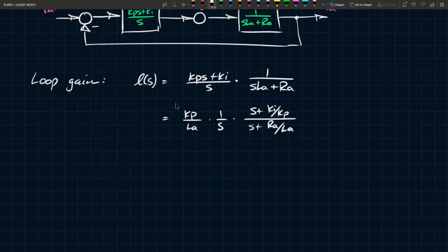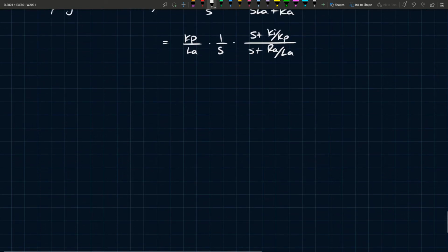Now what we do here is we do this thing called pole zero cancellation. So you cancel the pole of the plant with the zero of the compensator, meaning you'll be left over with an integrator. And we all know that integrators can track DC references without any issues. So this is a sort of little control trick that you would have learned, I guess, in an introductory control systems class. But we're going over it again here just to make sure everybody's on the same page.